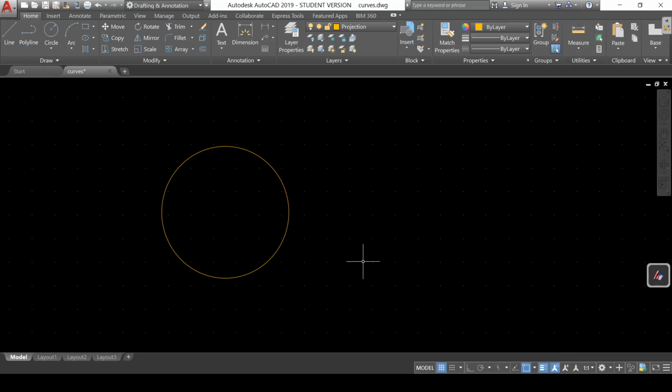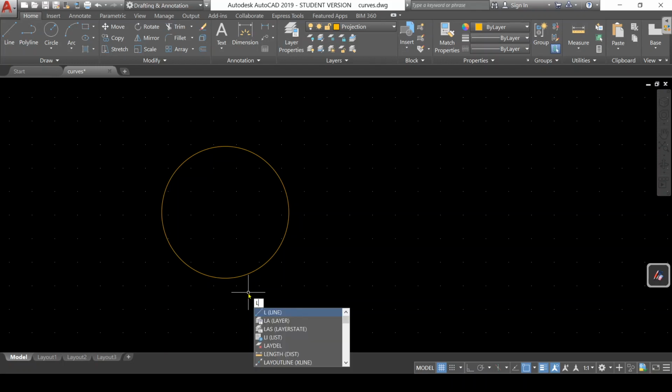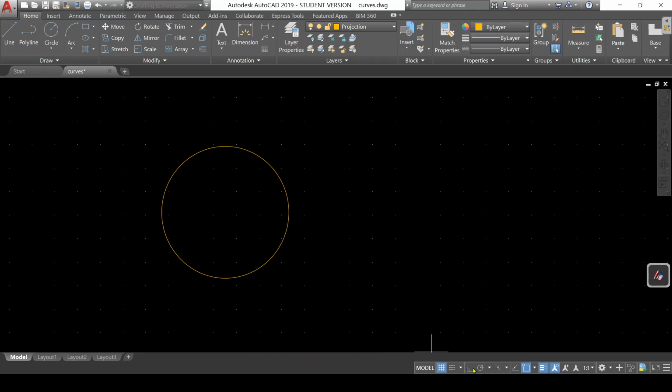Now it is rolling for one complete revolution. So what would be the distance traveled by this circle in one complete revolution? It will be equal to its circumference. So let us draw that straight line, which is initially in contact with this circle, first, and the length of that line will be equal to the circumference of this circle. Circumference is pi d, pi into 56. It is around 175.9, so let us take this as 176 mm. So this is that straight line.